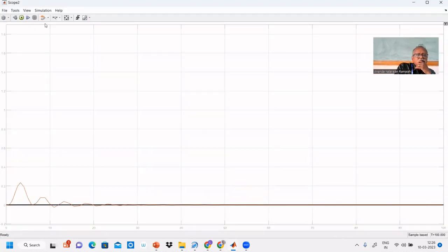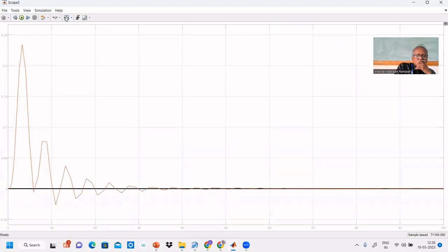You see that the feedback controller is red. That also controls. It rejects the disturbance, but with so many oscillations, because it tried to control after the effect was made in the output. Because of the disturbance, the process is deviated. Only after that will the PID controller take action. That's why it takes this much time.